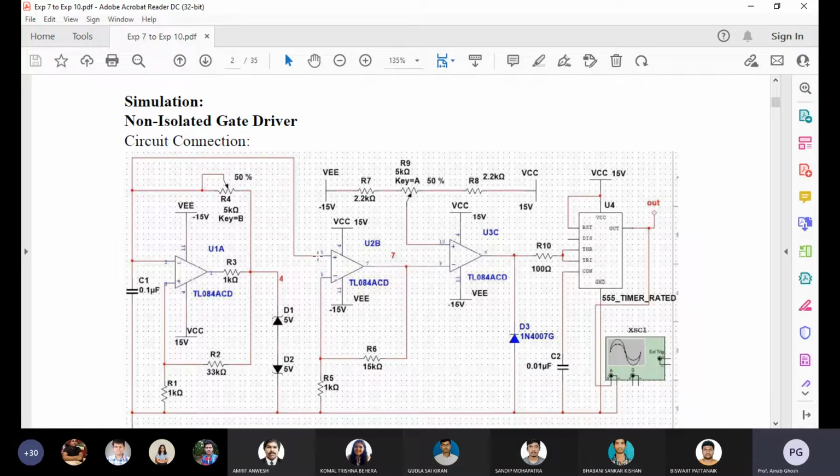So one oscilloscope should be connected to see how both voltages are coming and cutting each other. The DC voltage should come inside that repeating sequence. If it is not, you should vary the pot, and finally we will get the PWM.